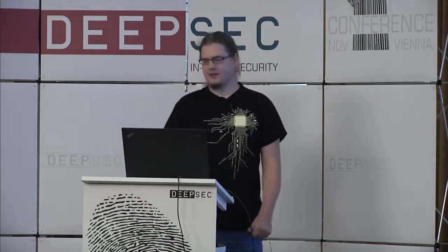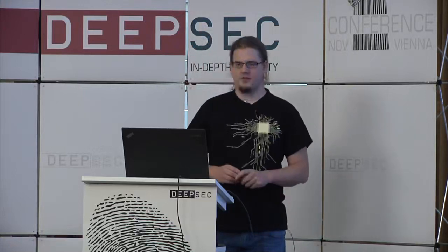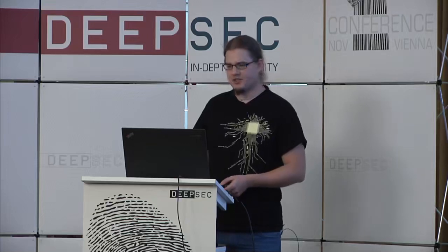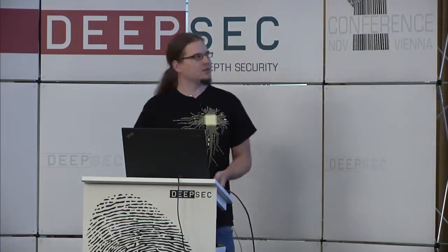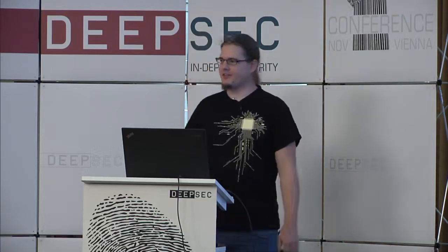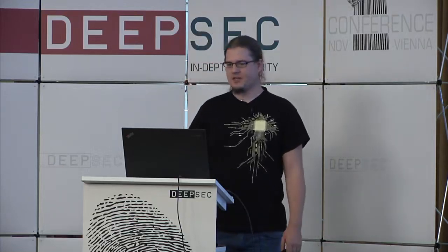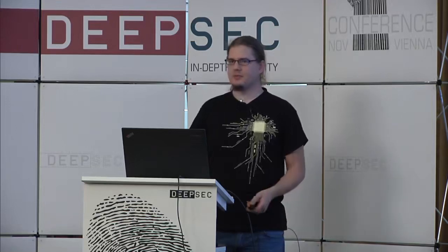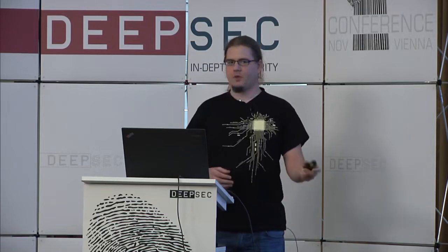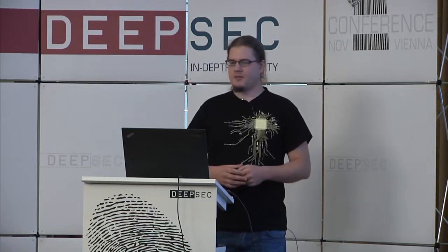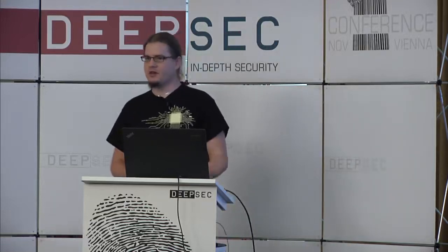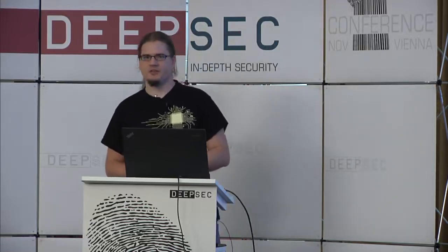Some interesting things from the data sheet, so that you get a quick overview of how this chip works and what interesting functions are in this chip. Well, this is what it looks like, at least the pinout. The first interesting thing we noticed was the SPI interface. This is just a simple serial interface that most microcontrollers have to communicate with other peripherals. In this case, you can use the SPI interface to program that chip and even to read out the firmware if it's not locked.